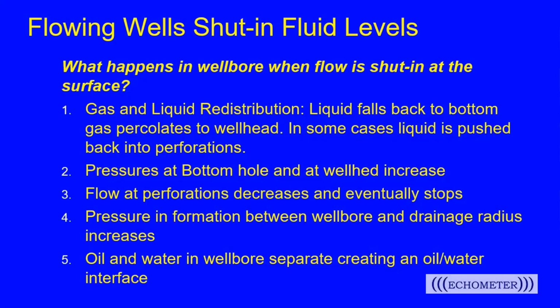Another scenario is where we have liquid in the well where we're liquid loaded. Our gas isn't being produced at a rate fast enough to carry the liquid out of the well. So we'll have liquid in the well bore, but even in that scenario, as we build up surface pressure on the well, it may push that liquid back into the perforations. And we're going to talk about what happens when that goes on, what liquids go back in first, and so on.